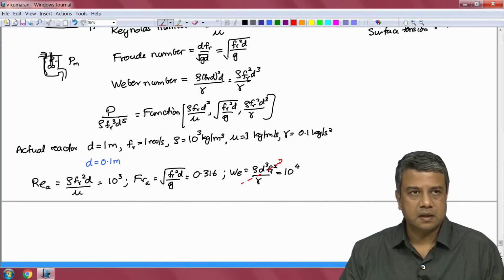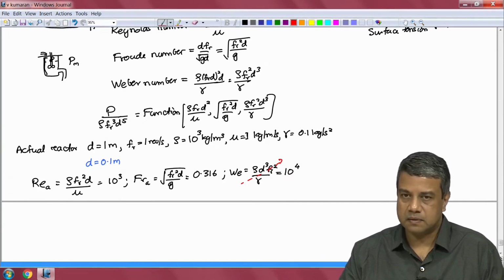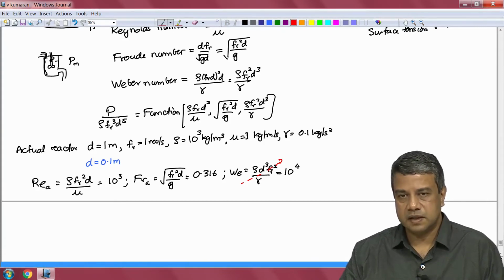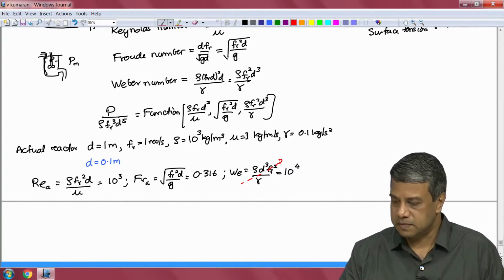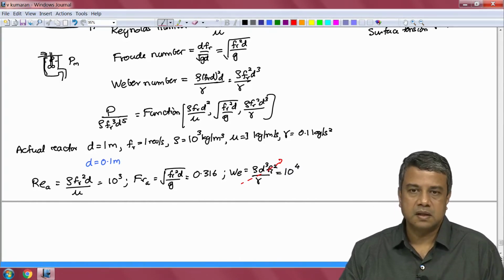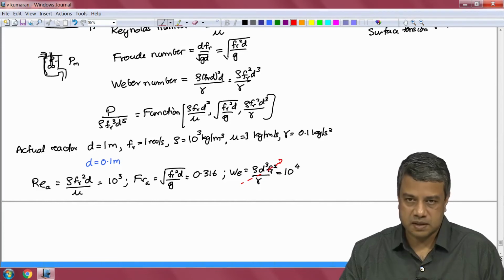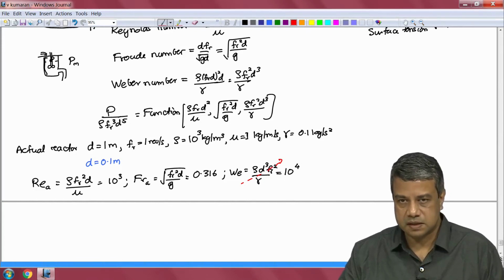As I said, even in the limit of high Reynolds number, when we saw the flow past a flat plate, for example, you cannot neglect viscous effects because they are important for transferring momentum to the surface due to the flow that is tangential to the surface.